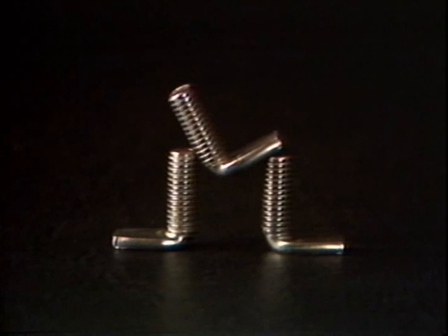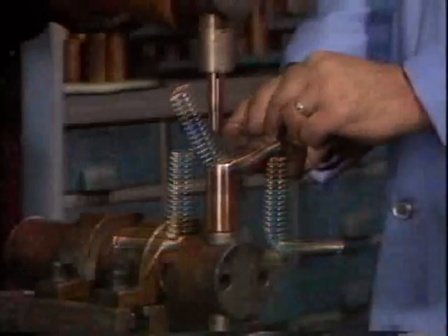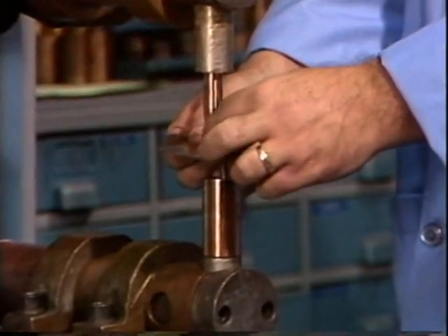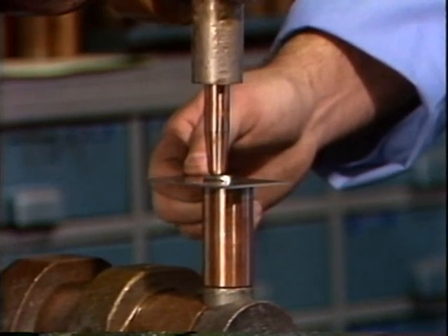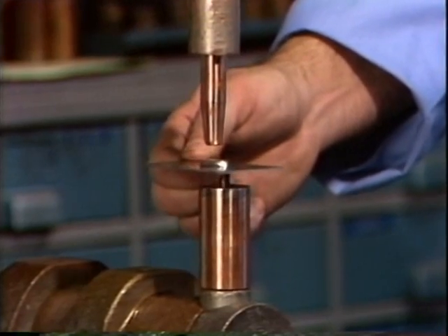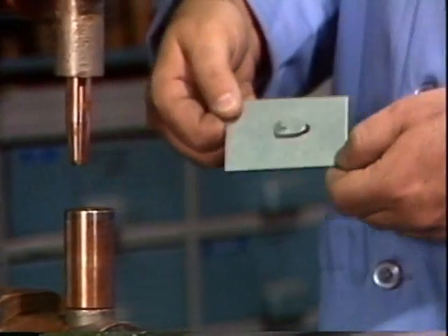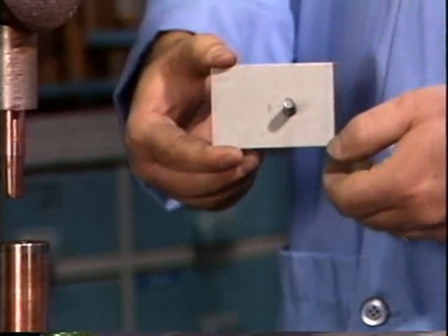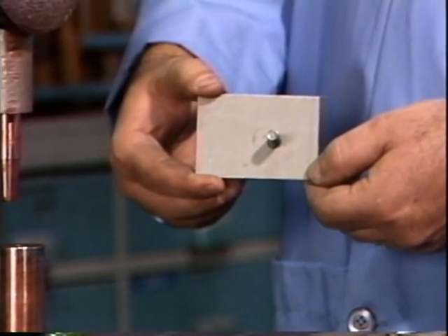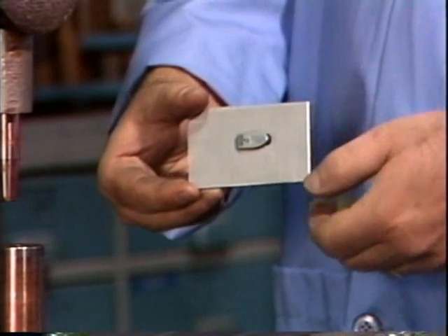Our SS-style spot weld spade screw has an ideally shaped flat spade at right angles to the threads. The spade permits welding to or through metal surfaces. The spade has been designed to be used with various sizes of electrode tips. It is designed to fit in confined areas such as narrow channels, walled corners, and in those applications requiring threads offset from component surfaces. Again, the smaller diameter electrode will be on the thicker material, in this case the spade of the SS weld screw.